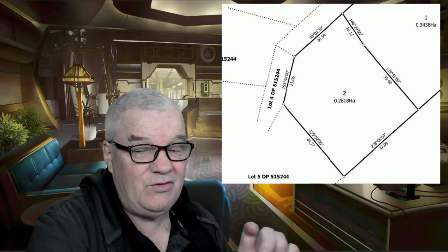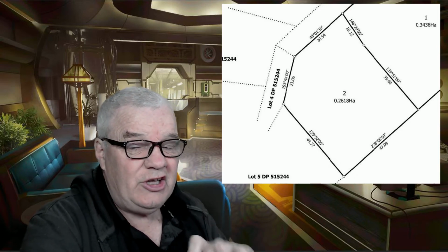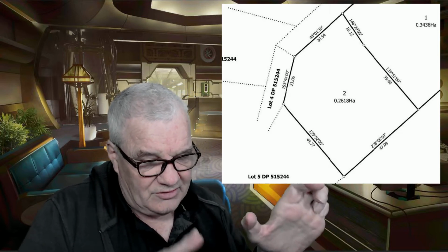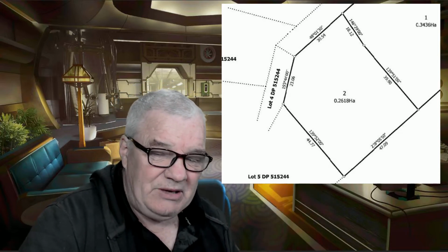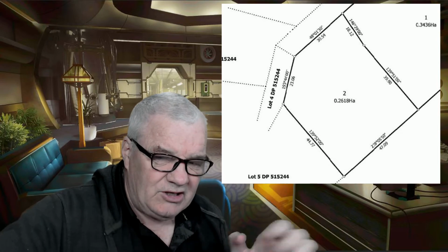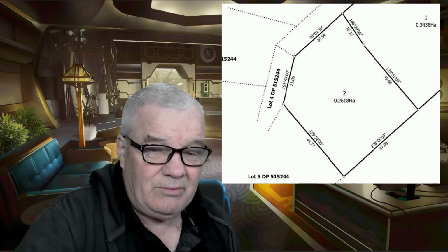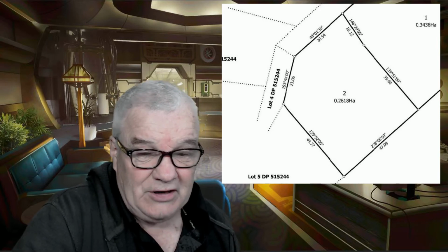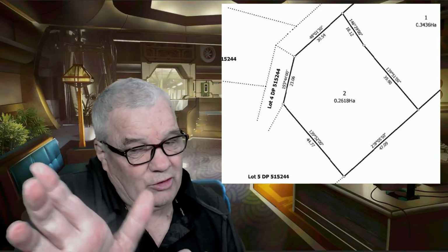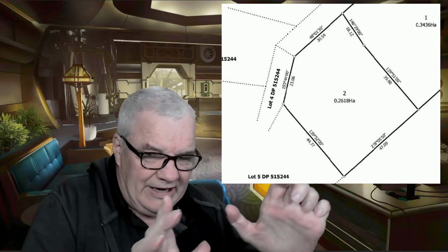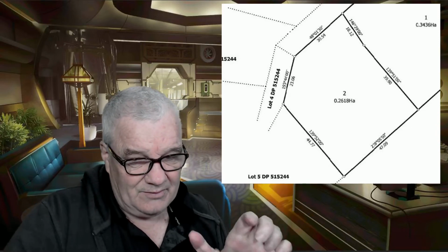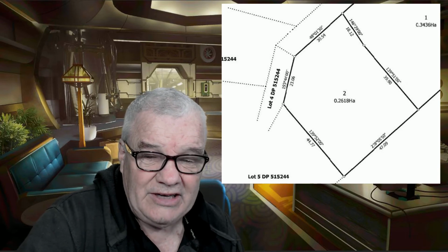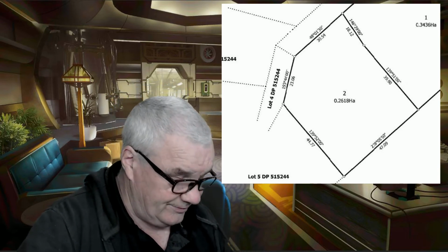But as I say, be very careful dimensioning off this model. Make sure the house can be positioned without putting any error from the boundary model into the house. So you might fix one corner and then fix the direction of the other wall so that the house can position itself, and you won't get any error from any of the other corners out to the boundary.